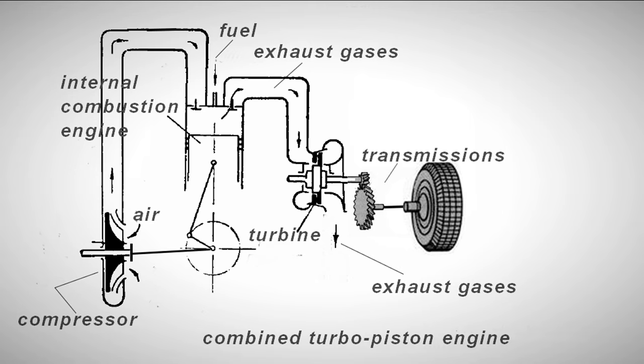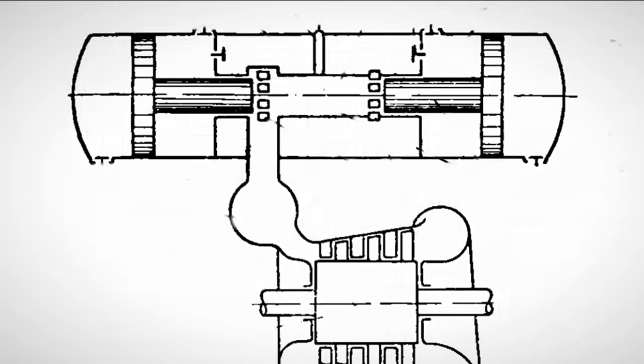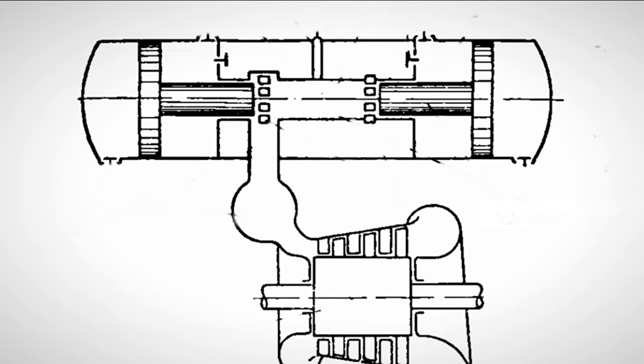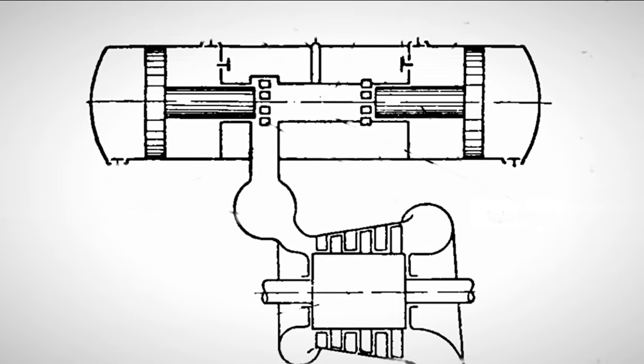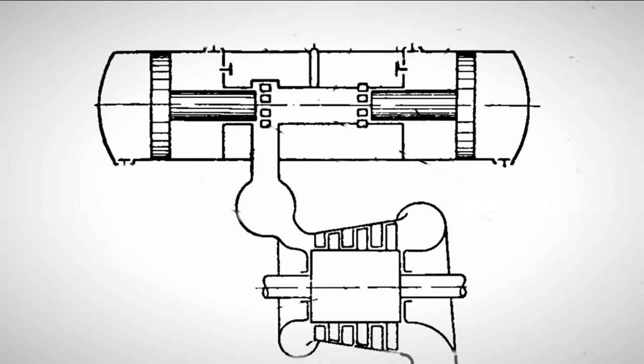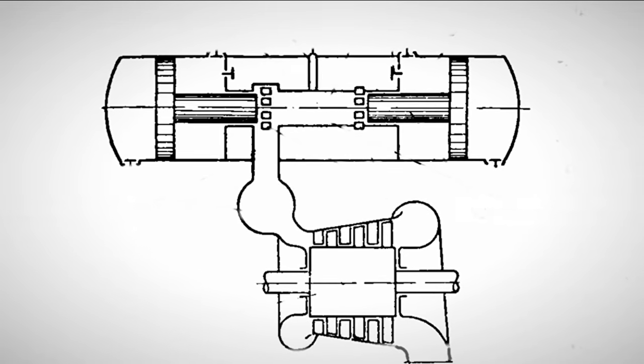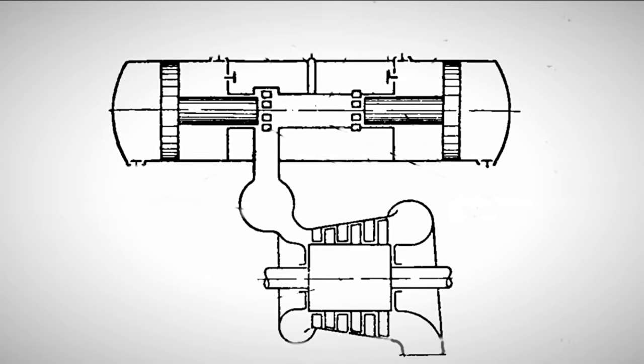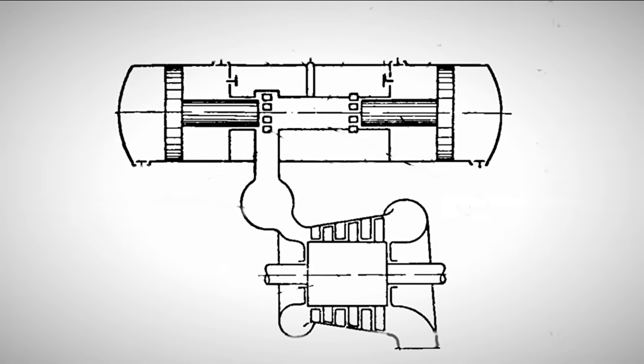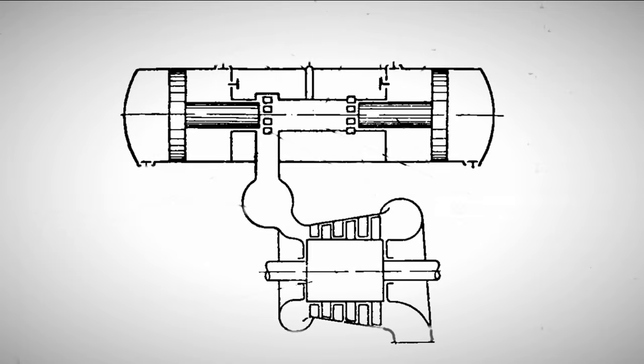Another question: is it necessary in this case to use a conventional internal combustion engine, with its crankshaft, connecting rods, camshaft, multiple bearings, and so on, to generate gases? After all, this task could be successfully accomplished with a simpler gas generator based on a free-piston engine, which combines both the combustion chamber and compressor. Although examples of crankshaft-based gas generators exist in mechanical engineering worldwide, free-piston gas generators are more common.